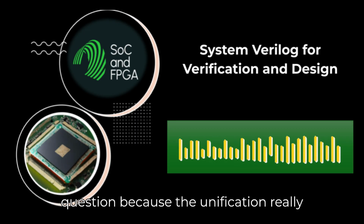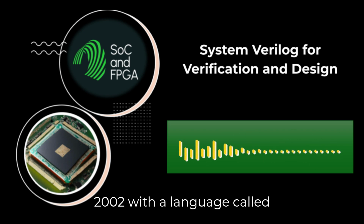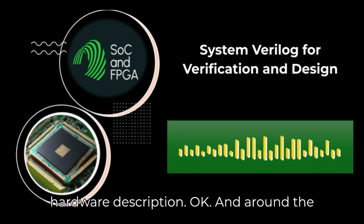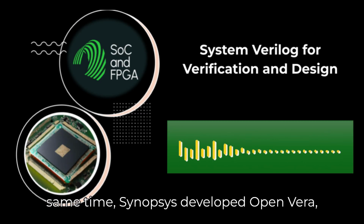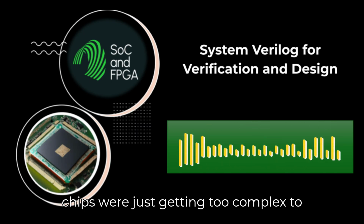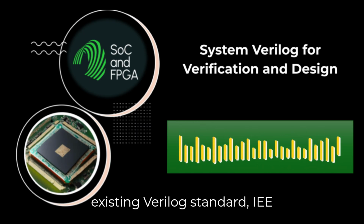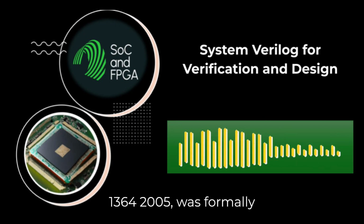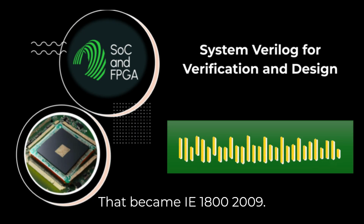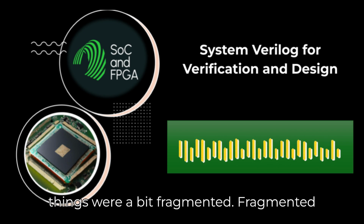That's a great question because the unification really is the game changer here. SystemVerilog's roots go back to 2002 with a language called Superlog that was aimed at enhancing hardware description. Okay. And around the same time, Synopsys developed OpenVera, which was specifically built to tackle the growing verification challenges. The chips were just getting too complex to test easily. Right. But the really pivotal moment came in 2009. That's when the existing Verilog standard, IEEE 1364-2005, was formally merged into the SystemVerilog standard. That became IEEE 1800-2009. So before that merger, it sounds like things were a bit fragmented.